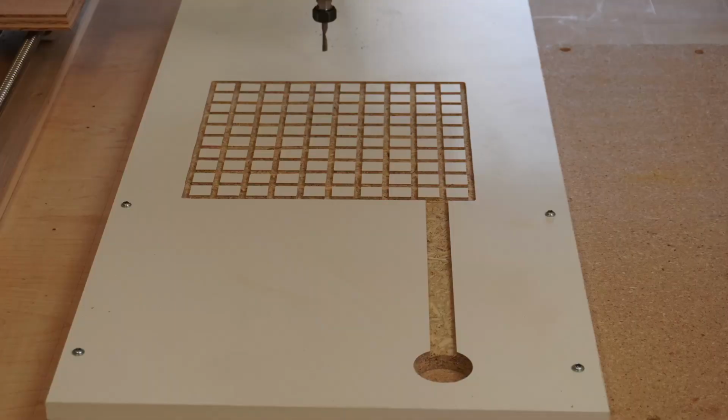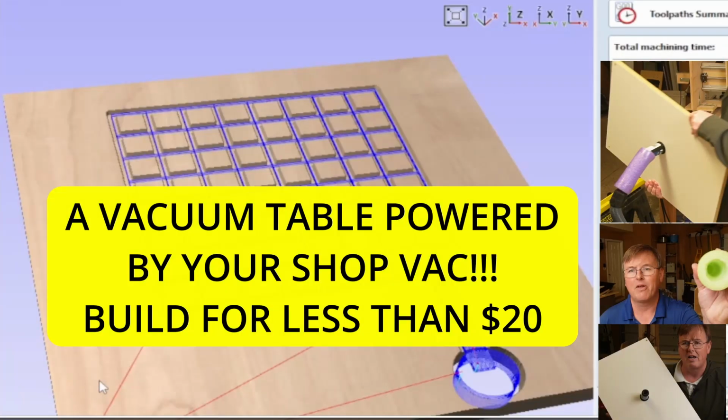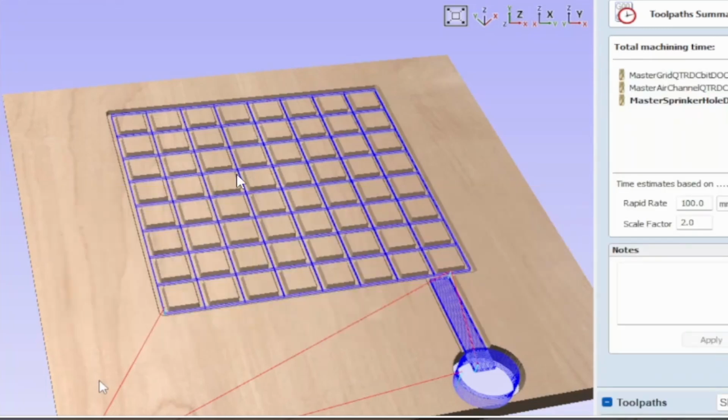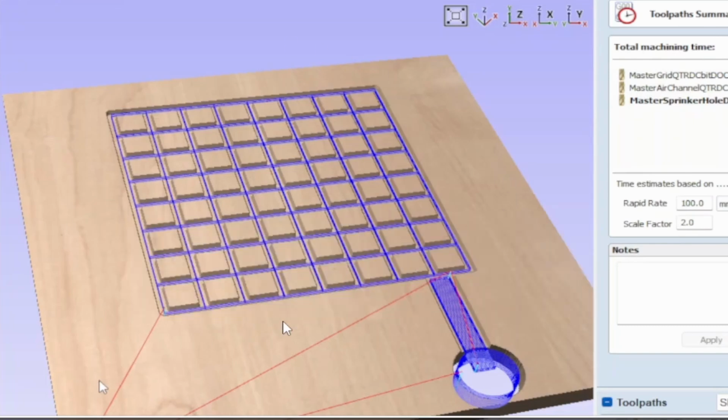In this video, I'm going to show you the most efficient way to create the tool paths for your vacuum table. In particular, we're going to accomplish this by, one, using the same size bit for this and this and this, which is a 1/4 inch downcut bit that will keep the melamine from splintering when you try to machine it. Number two, we need the grid that we create to be one continuous vector. I'm going to show you in this video how to do that very efficiently.